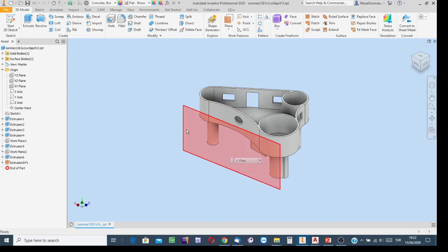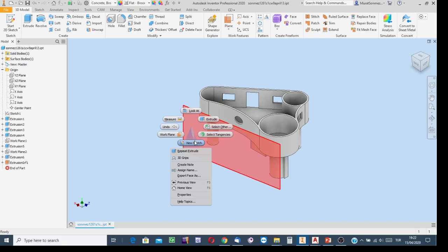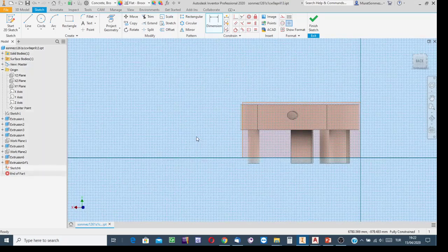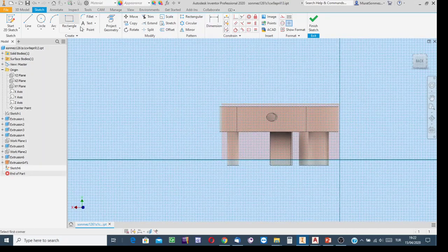And then on this surface take a sketch: right click, new sketch, and then the rest. Draw the necessary profile. Say that here we need to create a rectangular prismatic empty space, and then apply the project geometry process relative to the edge of the floor, and relative to this boundary of the cylindrical surface.